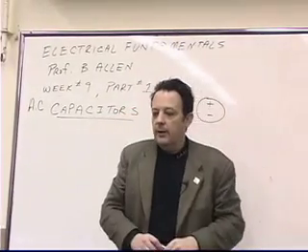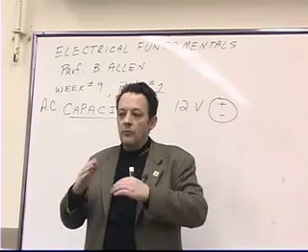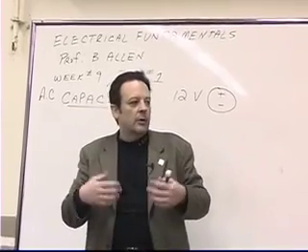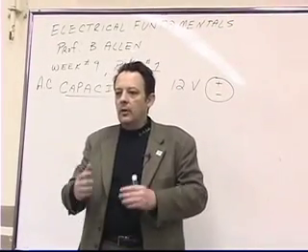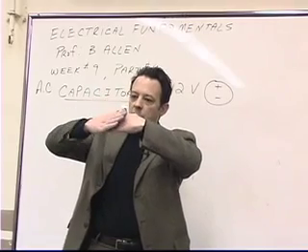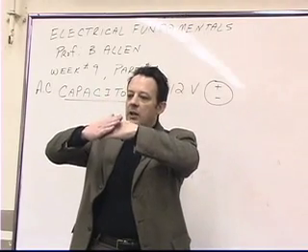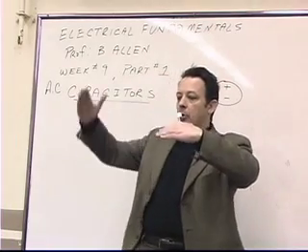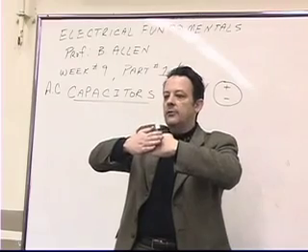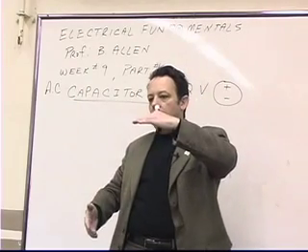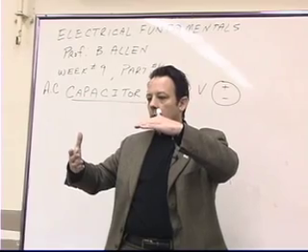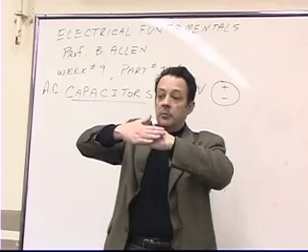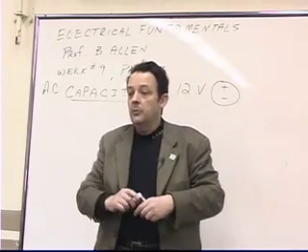In the case of industry application, we usually don't find that we use air for a lot of reasons. We use things like ceramic or rubber or other things that can allow us to take the plates and push them against each other, but have something wedged in between that keeps them from shorting out. Because if I just had a plate and I put another plate on top of it, they would short out against each other. But if I had a plate and I put like some oil wax paper over the plate, and then I put another plate on top of that, there wouldn't be a short because there would be an insulator between the two plates.